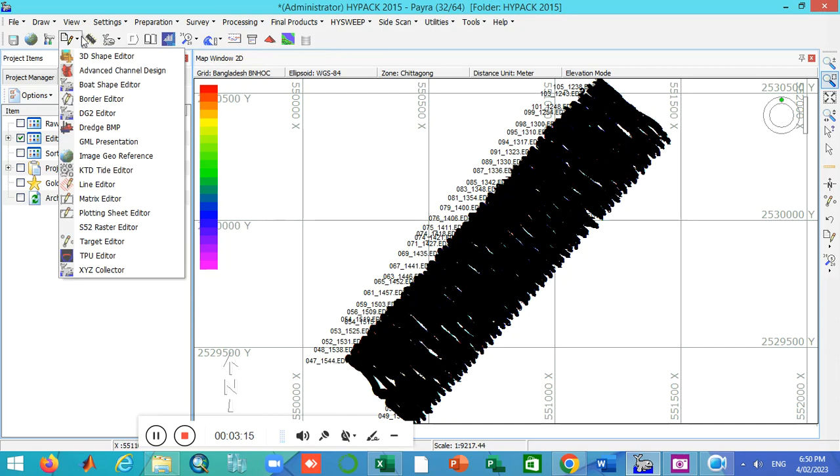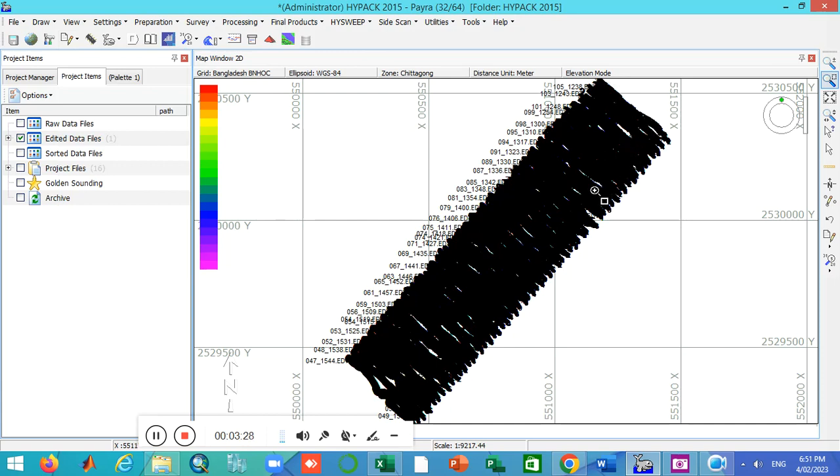Actually the more precise practice is to follow the middle part of the river, but the thalweg point may be shifted from this. If it is a meandering channel, then the thalweg point is shifted towards the outer bank, where there is some bank erosion, and on the other side deposition occurs. So in this video I want to show you our center line first. A tentative center line might be drawn in that fashion.